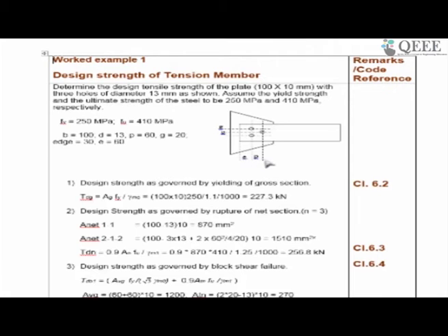Actually, the pitch plus end distance will also govern what is called block shear failure. So if I don't provide adequate end distance and pitch, I may have block shear failure in this member. So I have to check that. Let's assume some values for all this. The gauge distance g, you can see, between the 3 horizontal lines the distance is 20-20. So hopefully that adds up. That's why I have not shown the edge distance here.